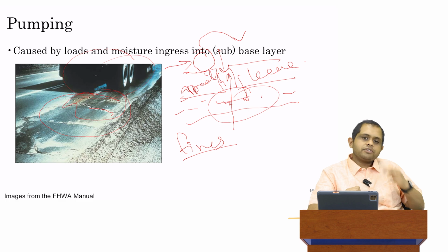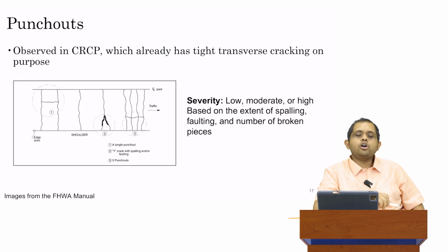Pumping is not generally classified into any kind of severity classification. All pumping is bad. And if you do observe pumping, particularly on highways where heavy vehicles are expected, it is important to quickly fix the problem, typically by reconstruction. So there's no severity classification for pumping. Okay, so that is pumping, and that then concludes JPCP.